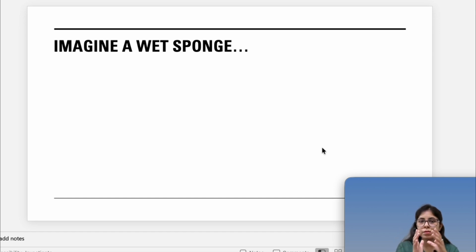The soil medium works the same as the sponge. That means in soil also, water will come out due to gravity. We will also get water out through our efforts by putting in more energy, and some water will always remain in the pores which we will not be able to take out.